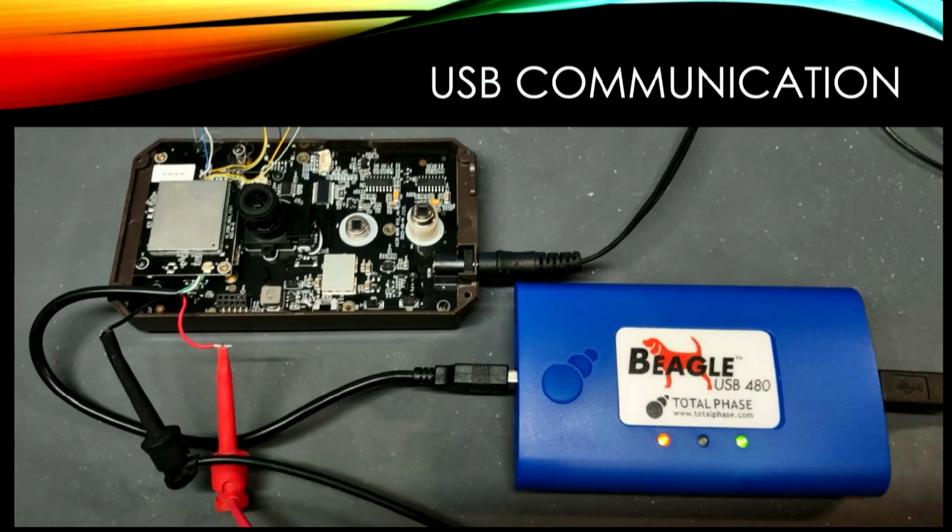Let's get into USB communications. The device I'm using is a Beagle. This is not cheap. It's about a $1,300 device. I am looking for somebody producing an open source one. The problem is if you look at USB sniffers, they're all inline USB sniffers. That means data in, data out the back side of it. If you're doing interchip communications, which travels 3 centimeters, you can't stick a device in between. Plus, it's usually a lower power level, so you'll instantly drain the circuit down and it will quit working altogether.